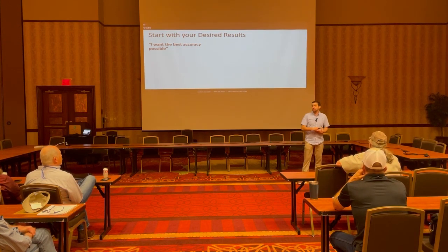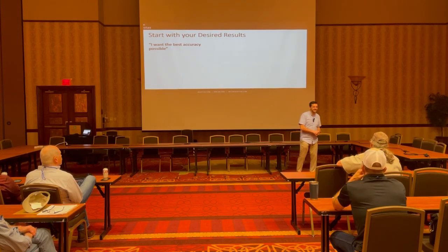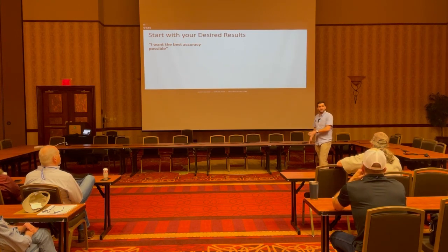Or other times, I'll even give a price quote. They say, I want the best accuracy possible, I'm going to fly this at 50 feet, I'm going to set 1,000 ground control points. I'm like, okay, that's going to generate 450,000 photos, and processing it will be many, many tens of thousands of dollars. And then they'll say, okay, maybe I don't want the best accuracy possible. I want good enough accuracy.